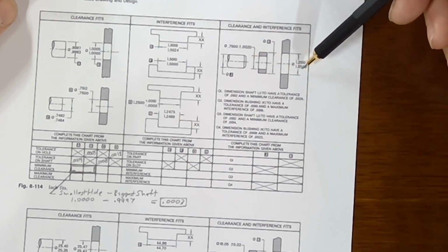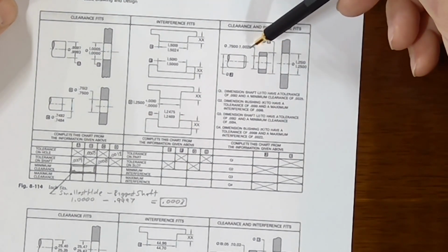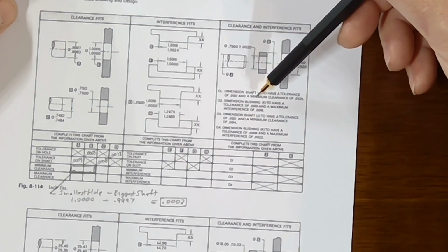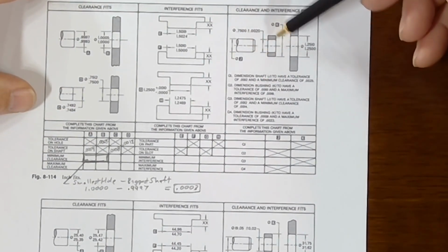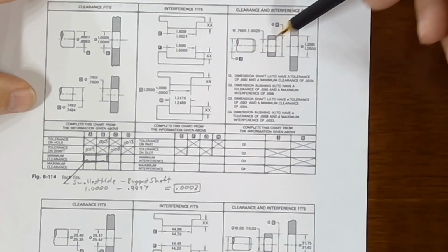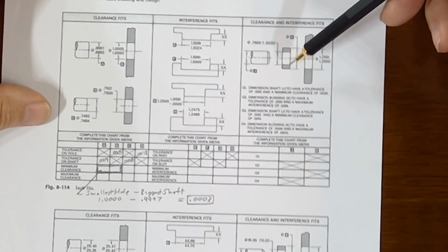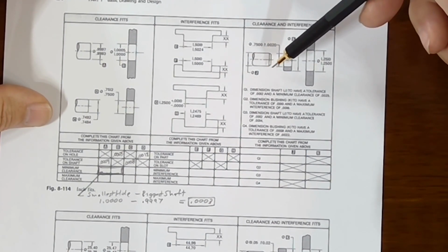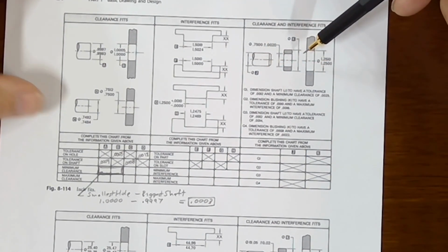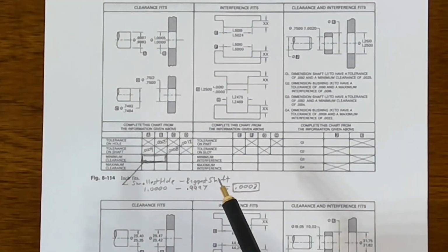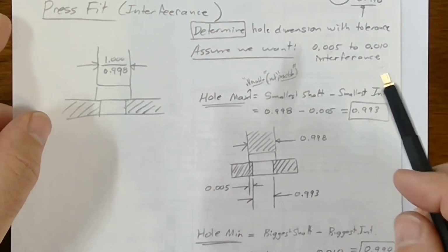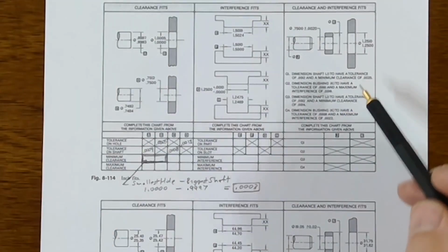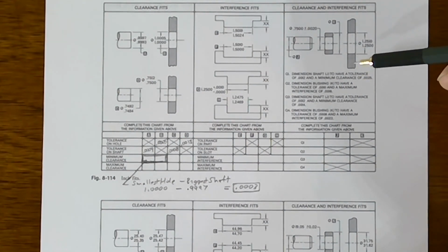So there's an interference between these two parts. And they're giving you some knowns, mins and maxes on holes and things, and then they're giving you some pieces of the tolerance. So you're going to have to do some algebra, right? This is a slip fit problem on this side, and this is an interference fit problem on this side. You have formulas for clearance fit. You have formulas for interference fit. It's just the knowns and unknowns change. So you may have to go back to these formulas and rearrange them algebraically to solve for what you need. Work through that from knowns to unknowns, and it's a little bit of a challenge.